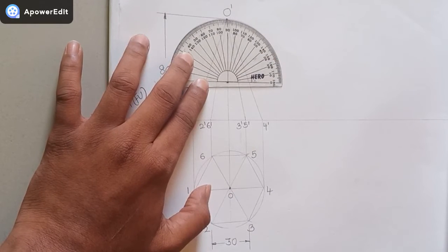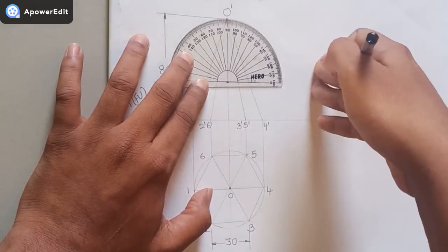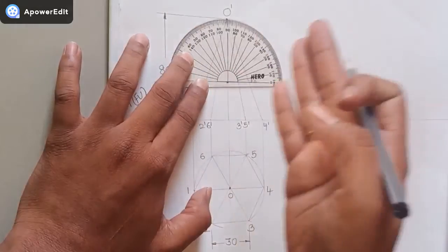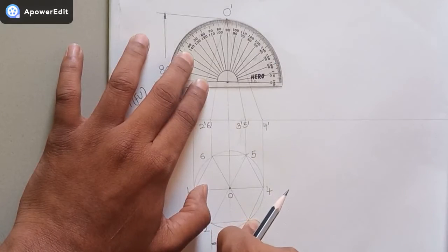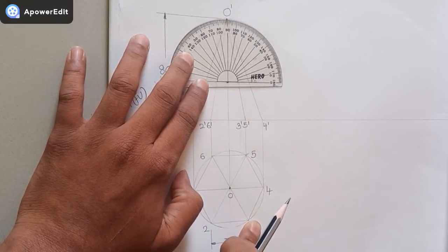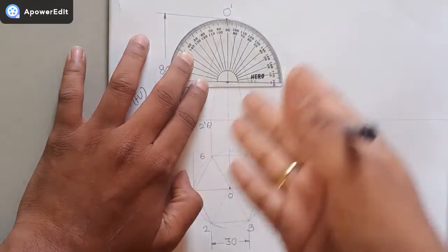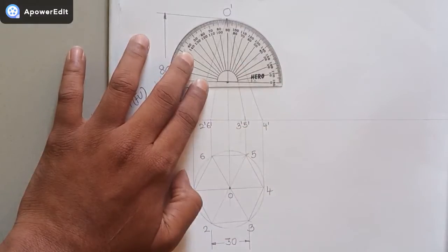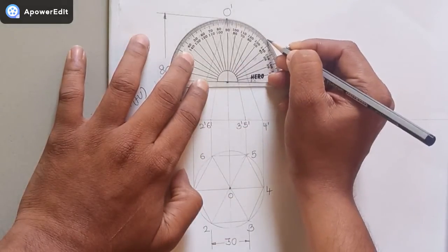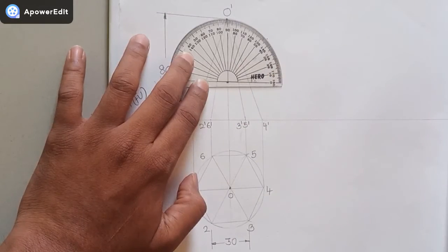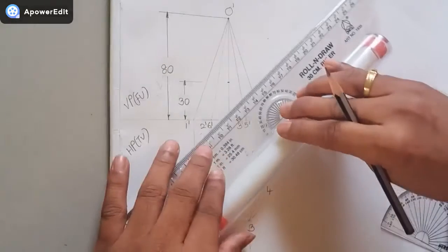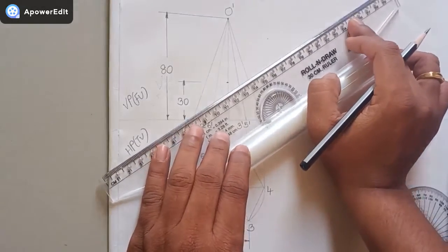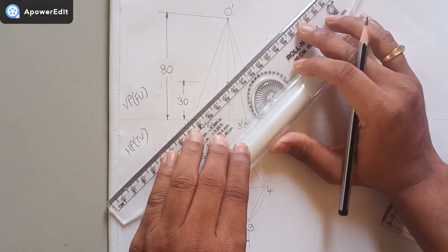See guys, the 45 degree angle can be marked towards the right hand side here, or it can be marked like this, either right or left. It is your own wish. You can do the problem as you wish. But remember, mostly the basic thing we follow is we draw the cutting plane towards the right. So here also I am going to do the same procedure. I will take a 45 degree angle and draw the cutting plane. See guys, the cutting plane is actually an axis plane, so it should be shown as an axis line. So I will show it like this. I am going to join these 2 points. Please pay attention. I am going to join these 2 points.